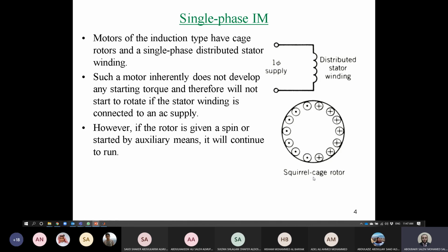We discussed previously the squirrel cage induction motor for the three-phase. It's similar to the three-phase, Shabab, where we have a cage with internal bars. Of course, here it's written plus or minus, or dot or cross. It means that the current is moving like that. Okay. So this is according to the direction of the flux, Shabab. The current will flow in different directions according to the flux under the pole. So we have one winding for the stator and bars in the rotor.